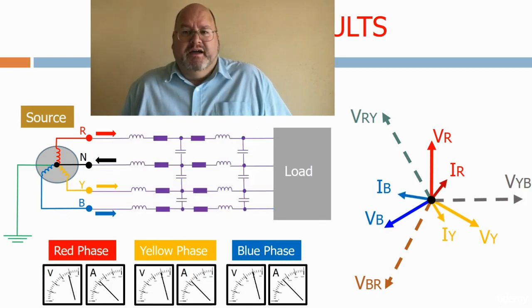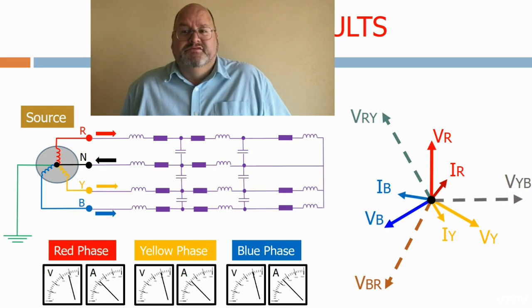The impedance of the line consists of resistance, inductance, and capacitance, which applies down the full length of the overhead line or cable. These will produce a total impedance for a line, which is called the characteristic impedance. The impedance of the load is normally inductive, but will obviously depend on the types of loads connected. For the transmission system, this load value will consist of thousands of individual impedances combined together.